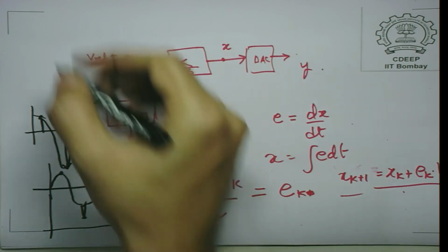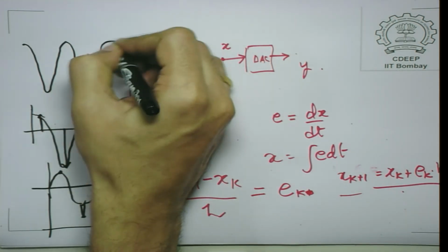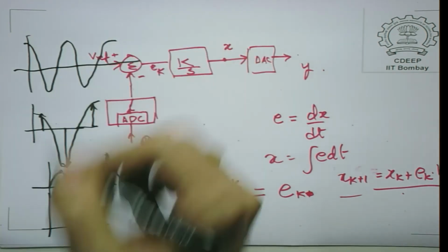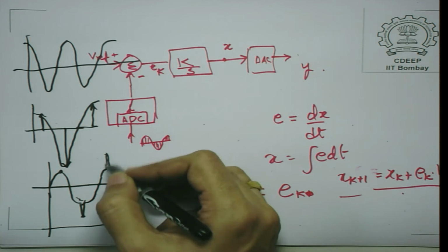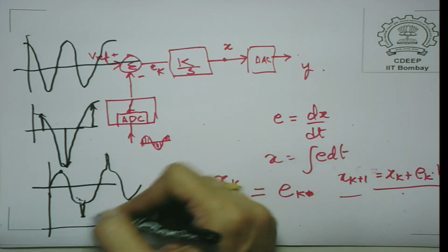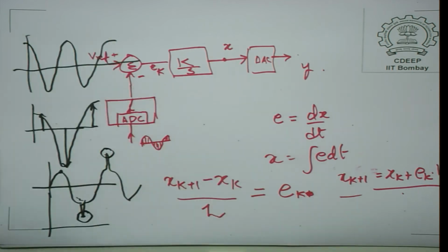You may in fact think that this is a waveform which is of this nature, which is not the case. The actual waveform is a relatively low frequency, but it has some spiky input. So, if you happen to sample these, you may get a completely wrong inference. This is a manifestation of a phenomenon called aliasing, where if you do not sample at a high enough frequency, you may have a problem.